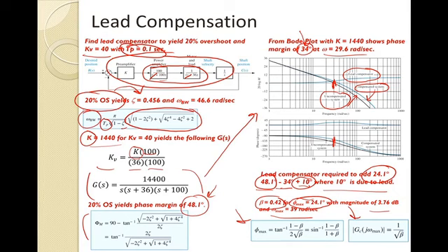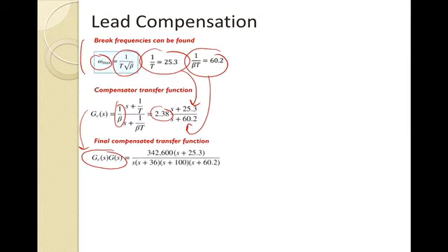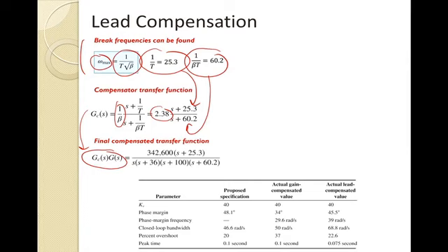So again, down here for the phase as well, here's my lead compensator. You can see, relative to that maximum frequency of about 40 radians per second is about where the peak is. So that's 10, 20, 30, 40. That's about where that peak is, okay, about 40 radians per second. And then again, you'll see that peak up, 0 to 45 here. So again, it goes up by about 24.1. So it's always good to go back and forth with your calculations, making sure you're plotting the right thing. And so again, I just wanted to show that final compensated transfer function.